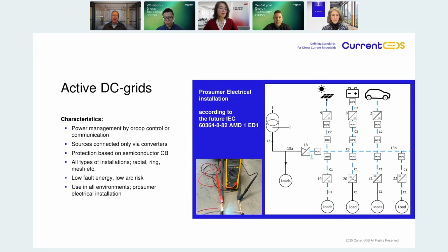The picture in the middle shows a short circuit flash at a 700 volt 70 kilowatt zone 3 cable, and I will come back to the zoning system later in this presentation. It's part of a movie where you can see that the arc flash risk is very low as soon as you go into zone 3.